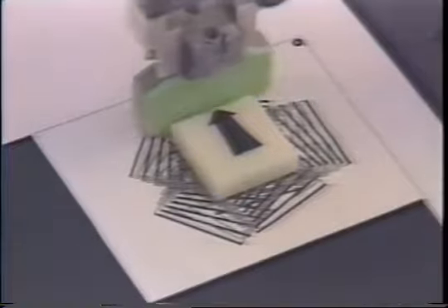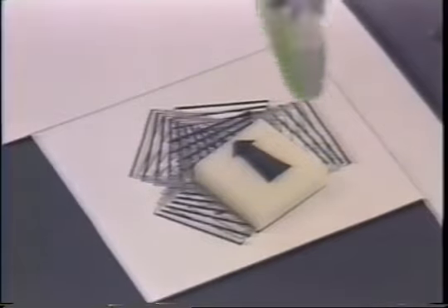To plan pushing operations, we specify the part's shape, center of mass, a set of pushing edges, and the friction coefficient. The computer automatically identifies stable pushing motions. These stable pushes are used by a non-holonomic path planner to find the pushing path. The plan is then downloaded to an adept robot.